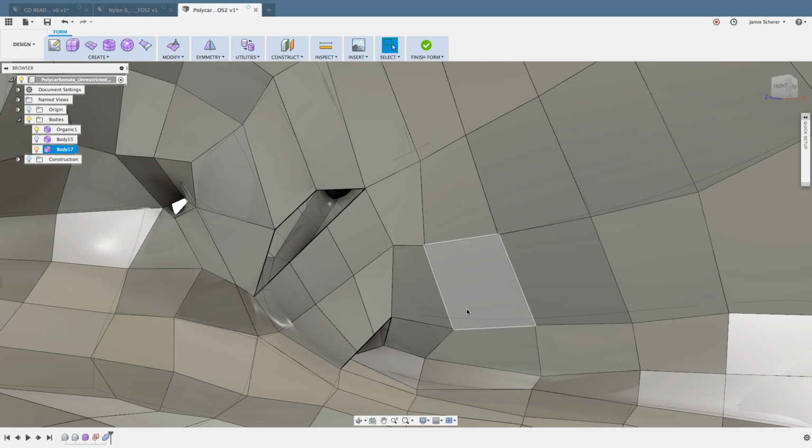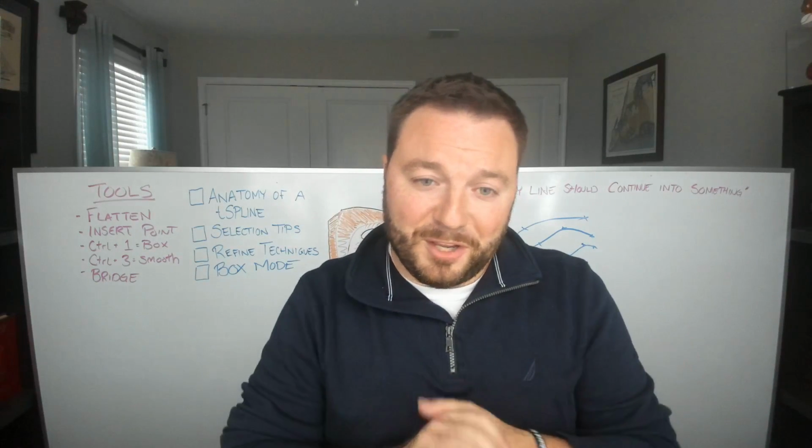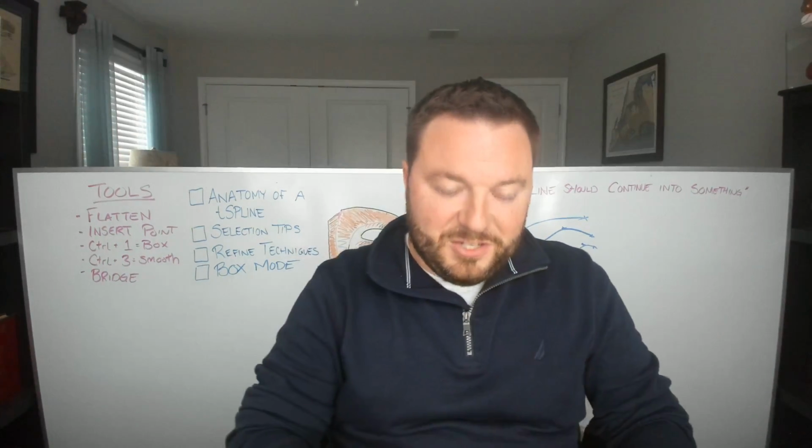You can see I bridged across those faces, but I have a hole. They're not connected to the other vertices on the other side. So what I'm going to use is a tool called Weld Edges. You'll find it in the Modify menu, and I'm just using the S tool and searching for it. I also have it in my shortcut toolbox that you'll see there. Now, sorry, I said Weld Edges. Let's rewind the tape. It's Weld Vertices. So my English is effectively not working for me today. So Weld Vertices is the tool that we're going to use. All right, let's jump back into it.